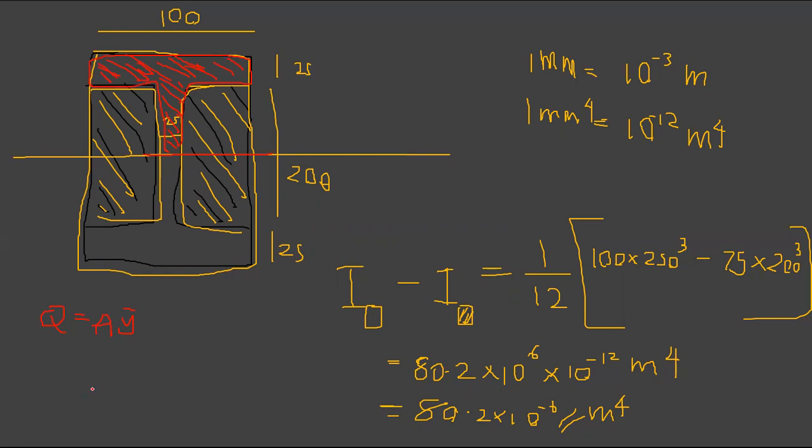So that's going to give you how much? I think you need to calculate it. The easiest way, because I need this from this axis, is to take moments about that axis to find the center of gravity.